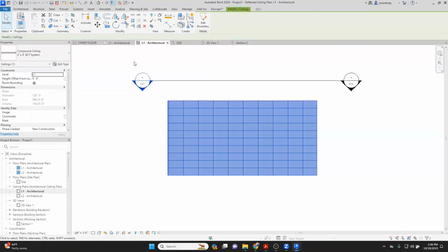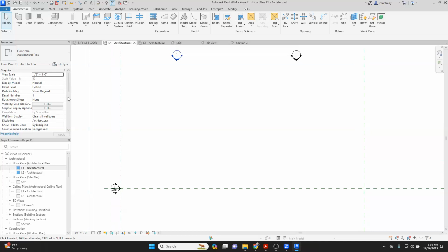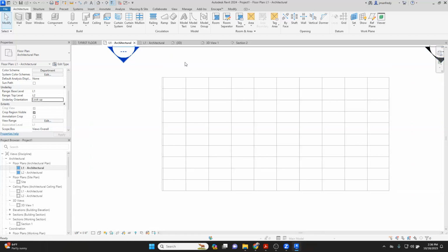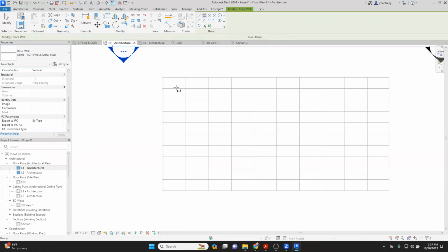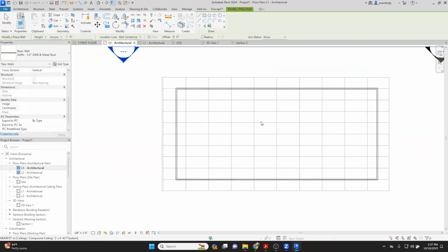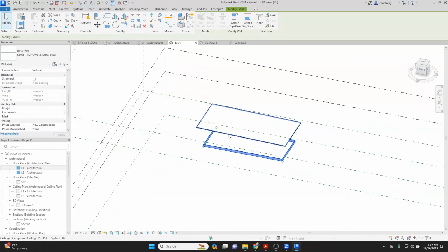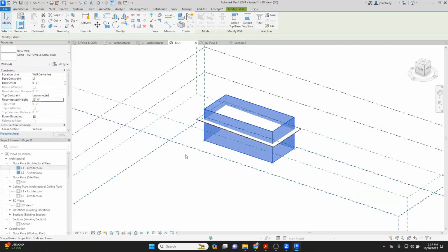So I got that. So what happens then if I'm on the floor plan and I show myself the ceiling plan with underlay? Right, here's underlay. Between the first level and the second level, looking up, is the reflective ceiling plan right there. If I draw a wall or a soffit, let's draw a soffit. Here. The soffit right there. So here's a 3D model. The soffit should be taller than the ceiling. Okay, here.